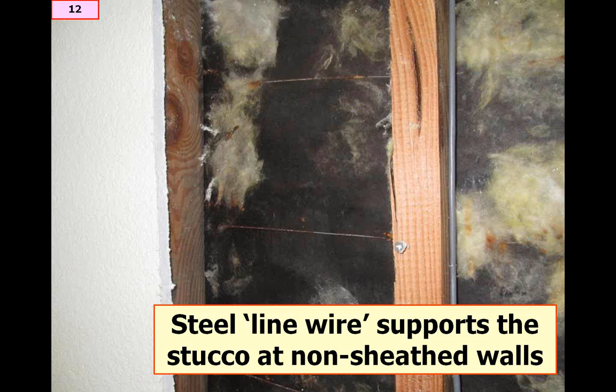Here's another example where we opened the unit from the inside, took off the interior gypsum board, and took out the batt insulation that was in the wall cavity, and found extensive evidence of moisture. The interesting thing for us, and for me from a forensic perspective, is that this damage and wood decay and fungal growth that we were finding within the wall cavity was limited to the ground floor walls. These conditions did not occur at the second floor units, and even at the ground floor, the conditions only occurred at certain walls, generally at bedrooms of these apartments throughout the complex.